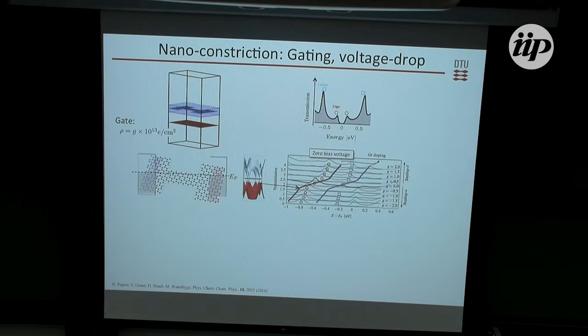So it's not that simple, and that's seen from this graph here, where we are at 0 bias voltage, and then we change the doping. This is N doping, this is P doping, this is again the transmission, just shifted, and you see this peak here, that's the center peak and the edge peak. I think I've switched the symbols, but never mind. What you can see is that they are shifting with the gating, but they're not shifting like the Fermi energy. This is the Fermi energy, this solid curve here. So it's kind of adding a non-trivial effect to this.